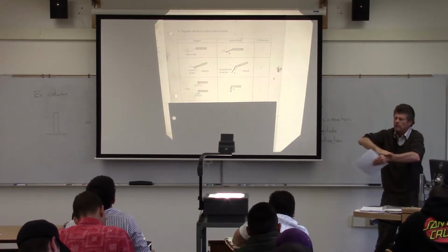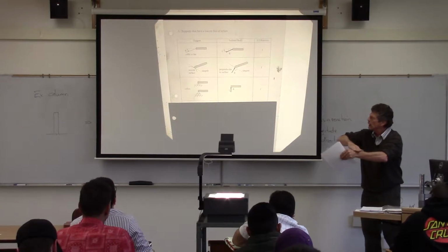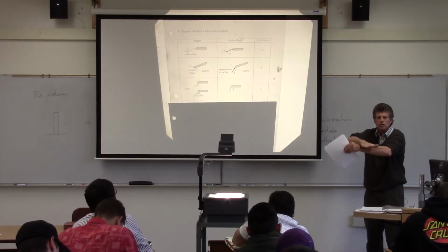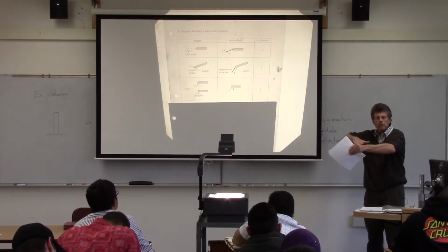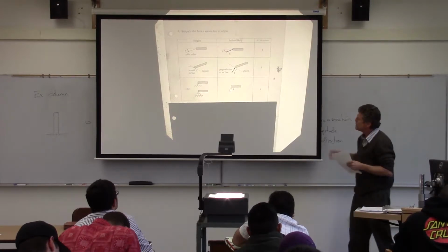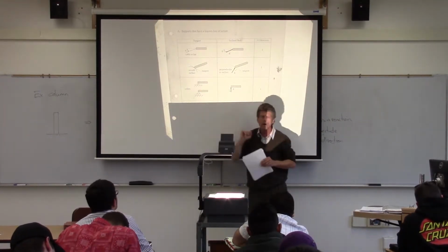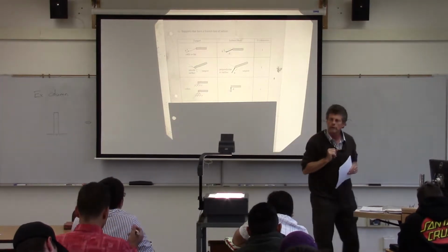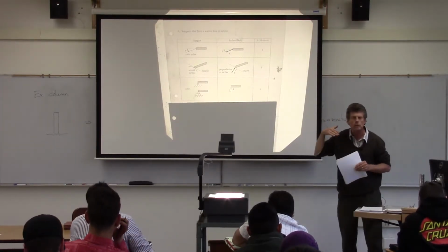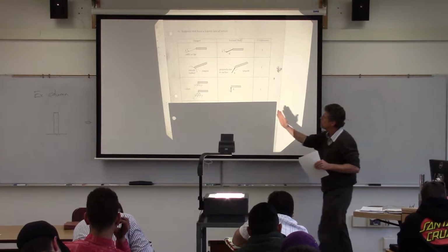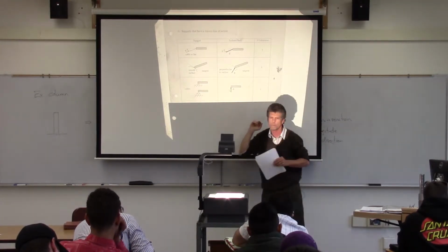So it's basically saying, I'm going to lay you on here, and if you expand, I'm going to let you slide. And if you contract, I'm going to let you slide this way. So again, think about the motion restrained. I'm not going to restrain any motion along the direction of the roller there, parallel to the surface. The only motion I'm going to restrain is vertical.